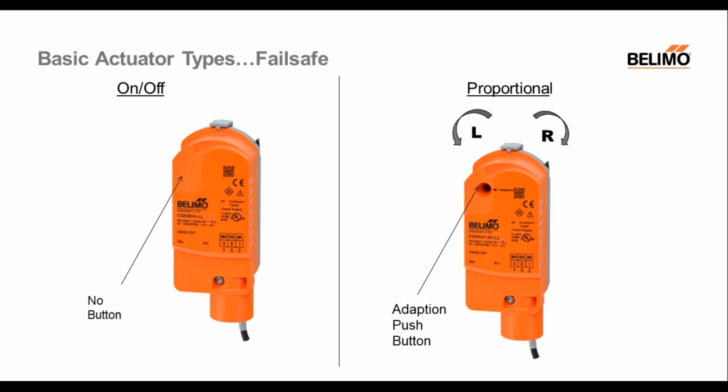And this is the information you would need to know to program into your controller for your 0 to your new set position. The failsafe on-off actuator is also available with an integral auxiliary switch. So if you had an application that requires on-off plus a switch, this on-off actuator does come with an end switch.